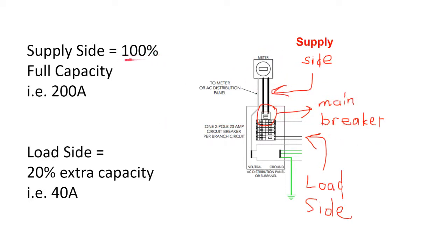That means if the site has a 200 amp service, then a 200 amp energy system can be connected to it. After all, the conductors feeding the building are rated for 200 amps. Regardless of whether the power to the building comes from the solar array or the utility, the power is still throttled by that 200 amp main breaker at the top of the electric service panel.